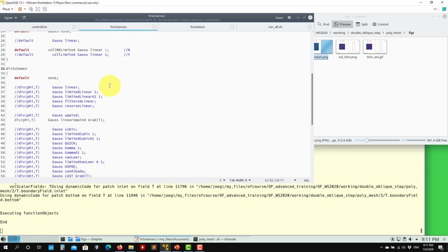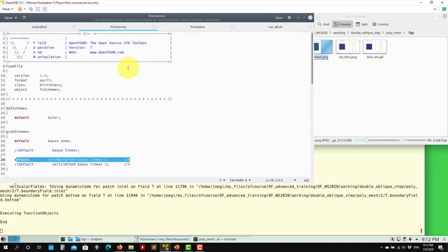Remember that you just need to play around with upwind, linear upwind, and a good TVD that can be the minmod of one layer. That's all that you need to know there. And also be careful with the gradients. Sometimes the gradients might be the problem, so you will need to bound that. So always leave the gradient limiter on.